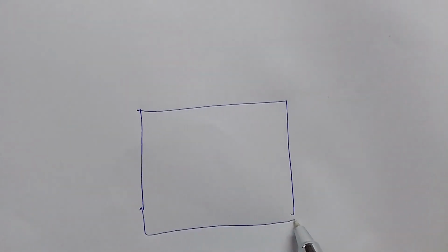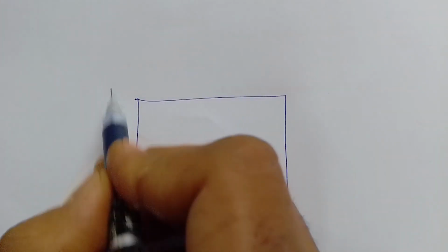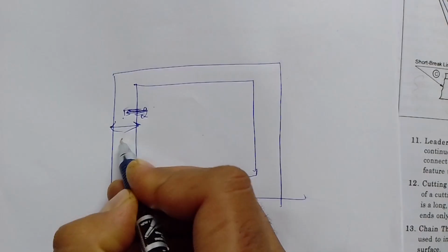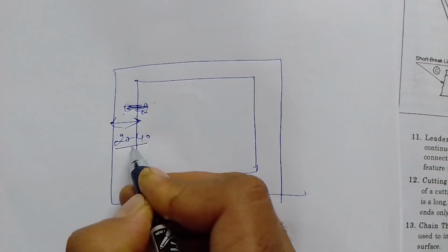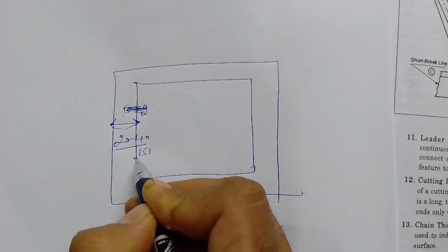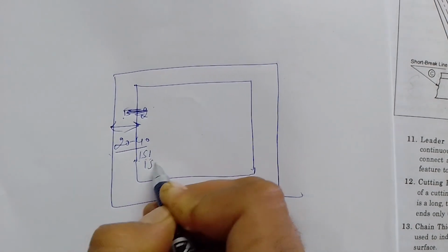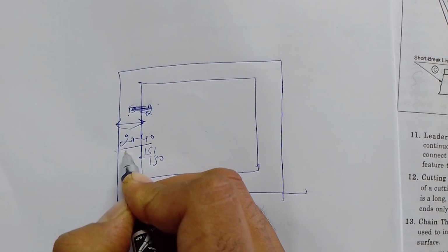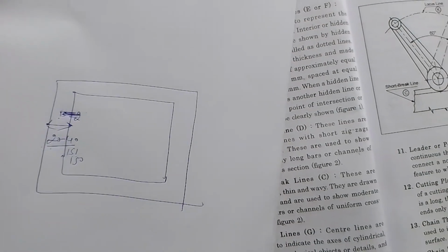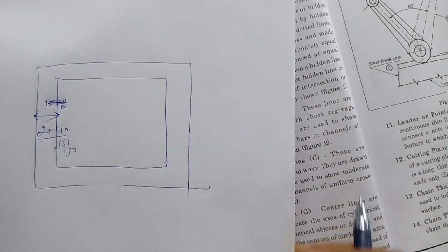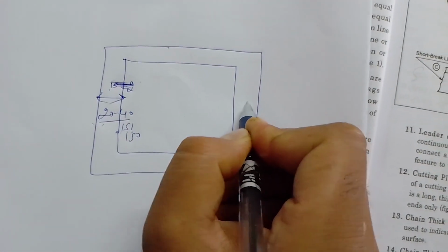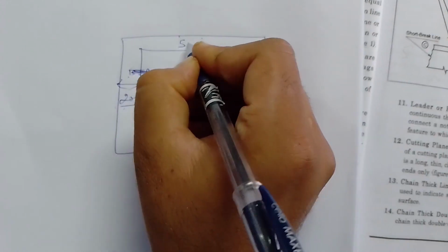Margin lines are called hashiya in Hindi. Like this is our drawing sheet, so this margin is 40 mm from the left side according to ISI, Indian Standard Institute, or ISO, for the untrimmed sheet. Just let me show you this A4 size sheet. This is trimmed, cut at 90 degrees from here, and the right margin and the other side margins are 5 to 25 mm.